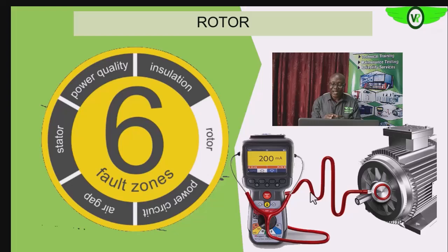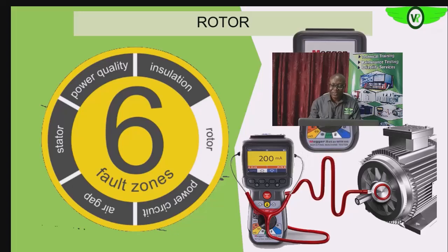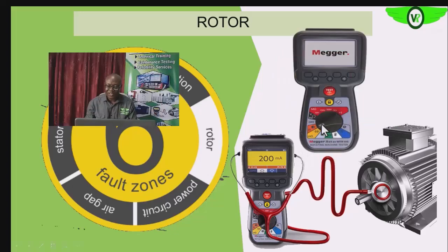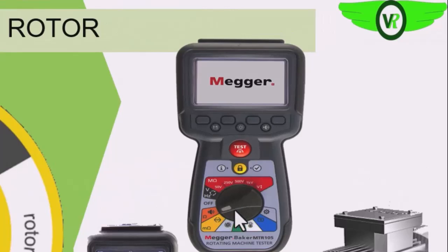Okay, so when there are problems, especially when residual flux or magnetic field in the rotor is more than what is normal, we'll see it during that rotor influence test. So in doing that test, you just take the selector switch to the inductance, capacitance, and resistance test selection.